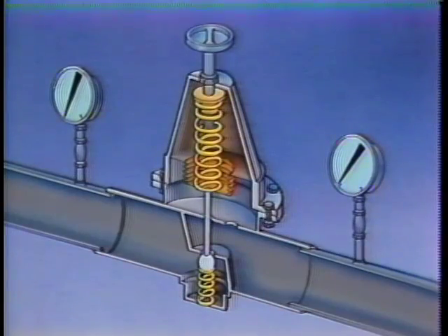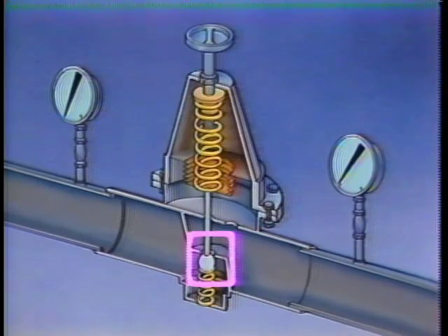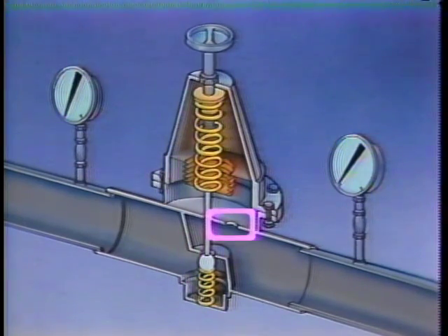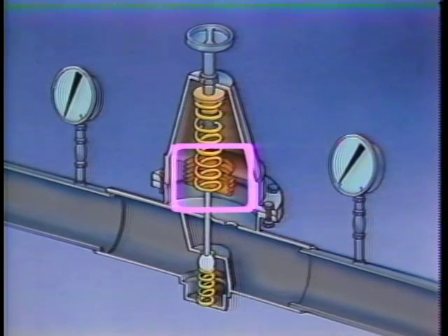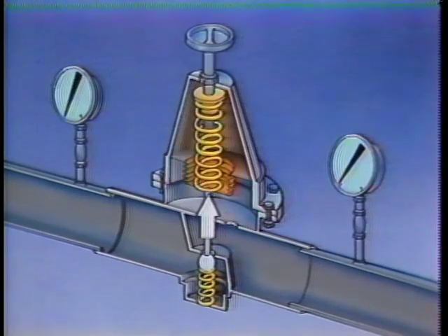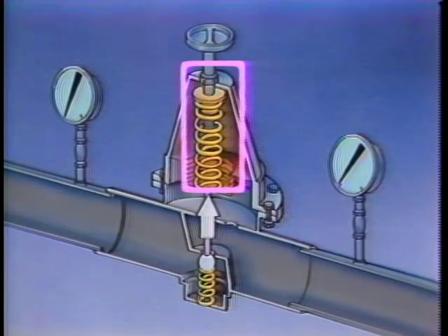There are two separate design styles for PRVs, each with a number of possible valve and actuator variations. Direct-acting PRVs are the least complex type. Like the multiple component automatic loop, there is a variable restriction orifice, the valve and seat. The downstream pressure is sensed through porting inside the body by one of several devices, in this case, a bellows. The bellows also serves as the controller because the outlet pressure is opposed across the bellows by the set point device, a regulating screw and spring.